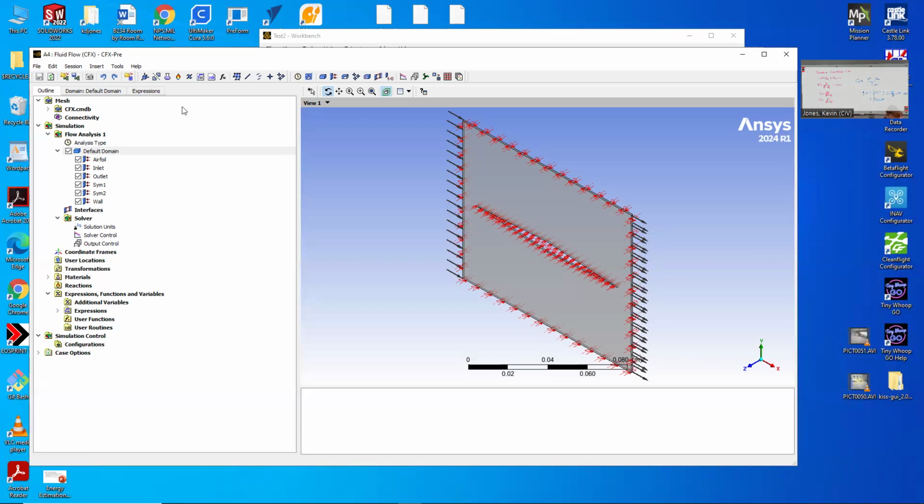I think the last one we'll probably do is a 3D version of this basically, and you'll do it at angles of attack in both subsonic and supersonic. In both subsonic and supersonic, it doesn't want to really separate, for two completely different reasons. The swept diamond airfoil canards on it just work really well.